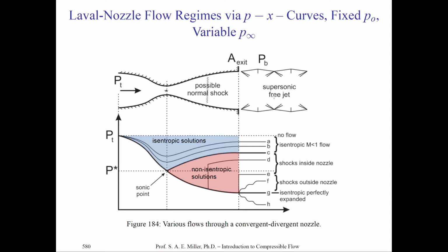The fully expanded pressure in the nozzle exhaust is derived from the Mach number of the ideal flow through the nozzle based on the area ratio of the nozzle, and of course the ambient pressure. So that's P infinity, and P must be balanced with the Mach number associated with the design Mach number based on the area ratio of the nozzle. You can find those from your equations on your equations sheet.